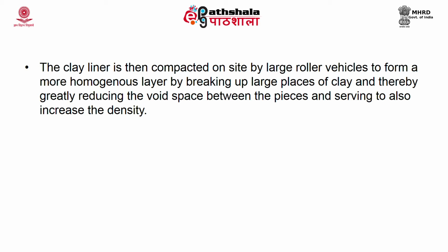The compaction done by moving a large roller vehicle over this clay liner will reduce the void space between the clay particles, and it will also increase the density of the material.